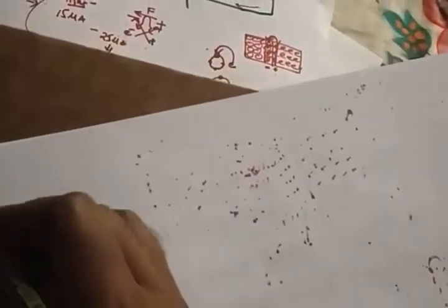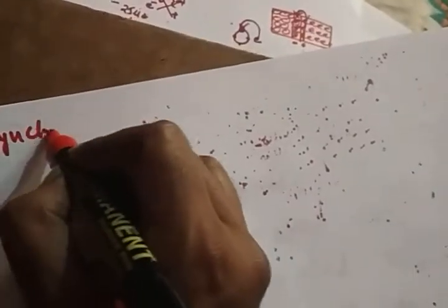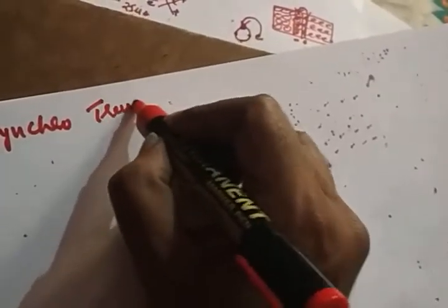I don't want to discuss synchros in great detail, right? We can call the synchro a transducer. So what is a synchro? A synchro transducer converts the angular position of a rotor to electrical energy. A synchro consists of a transmitter and a receiver. The angular displacement is converted to voltage, that is a synchro. It's nothing but an error detector that you can use in control systems, right?